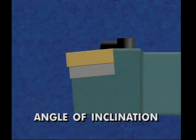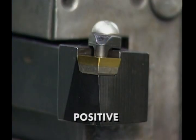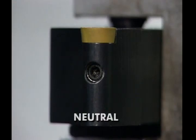Several angles are important when introducing a cutting tool's cutting edge into a rotating workpiece. Those angles include the angle of inclination, which, when viewed from the side or front, is the angle of the insert seat or pocket in the tool holder from front to back. The angle of inclination may be positive, negative, or neutral.